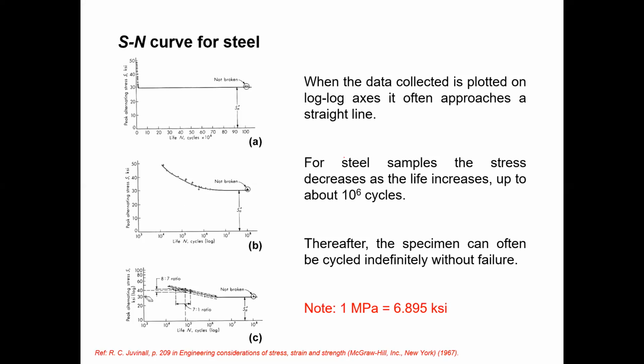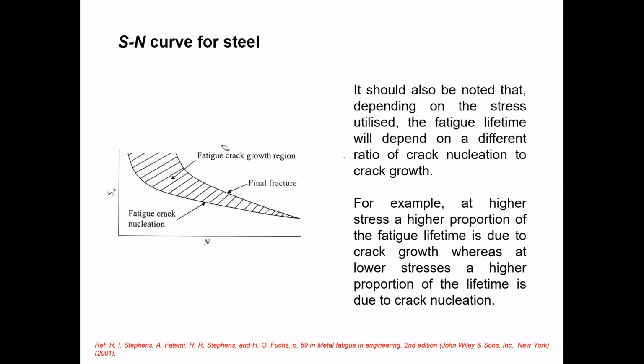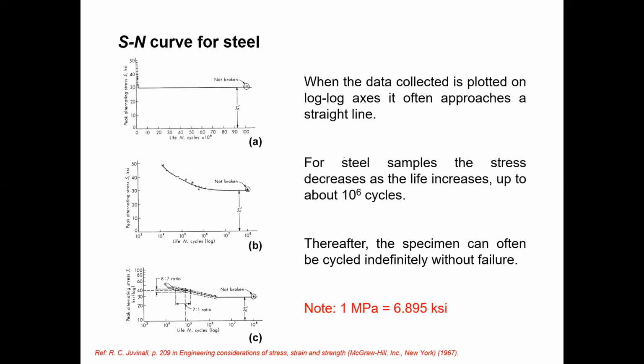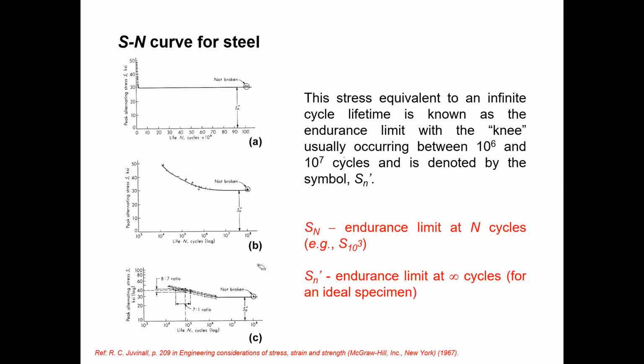So you can see here another important thing. This is the upper boundary, lower boundary also. So in this band we will get the average line, and you can see the upper boundary and lower boundary as well. And yeah, I already explained that. If that particular material is after this point, the number of cycles to break it is infinite. So even though you apply an infinite number of cycles, it will not break.